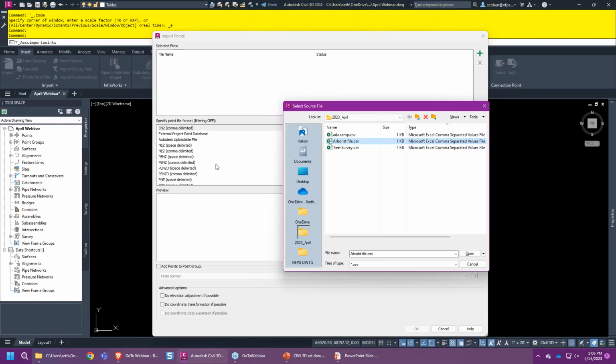Many times throughout whatever you do in civil engineering, obviously a lot of other sub-consultants don't have Civil 3D. They may not even have actual civil engineering software. They're using something totally different. For instance, if you're getting borings, the boring engineer may actually just have their own little GPS unit, or they give you KML or something like that, all right? So there are many ways that you can bring the data in with COGO points to leverage a little bit of the Civil 3D functionality.